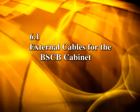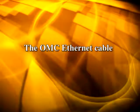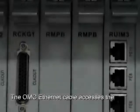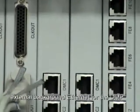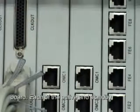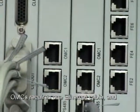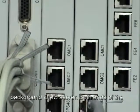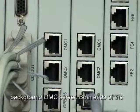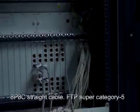6.1. External cables for the BSCB cabinet. The OMC Ethernet cable. The OMC Ethernet cable accesses the external background Ethernet for the OMP board. Each of the active and standby OMCs require one Ethernet cable, and they are connected to the same hub as the background OMC server. Both ends of the cable are crimped shielded plugs using 8P8C straight cable.